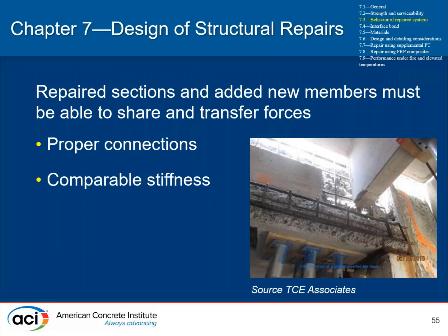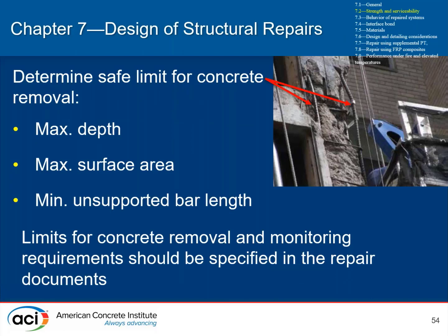The ultimate goal when repairing these structures is that they're going to share load. And so, to go back to the column example, just taking a step back, at the end of the repair, what's been installed has to work concurrently with the original construction. In some cases, good column repair requires deloading of the column, et cetera, to provide the ability for the new repair material to work in concert with the existing concrete. And the material properties that impact shrinkage and volume change become very important.